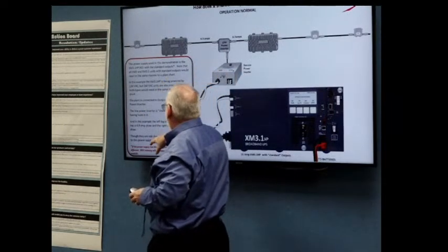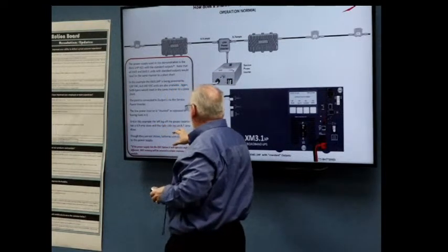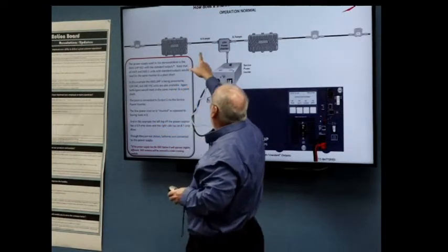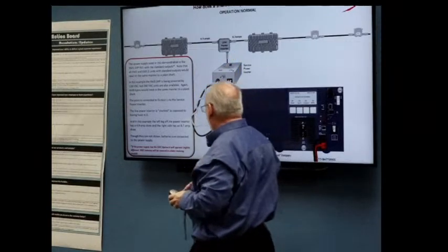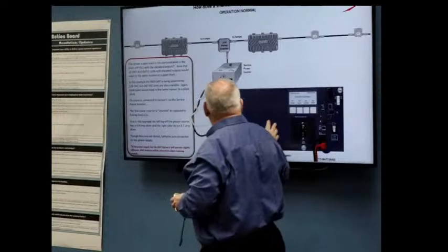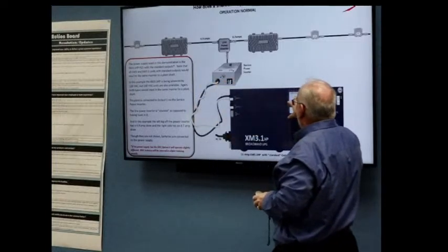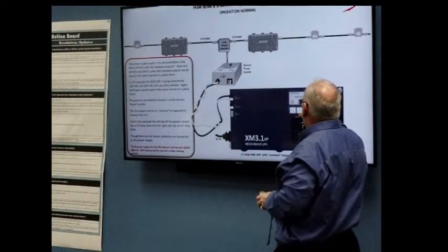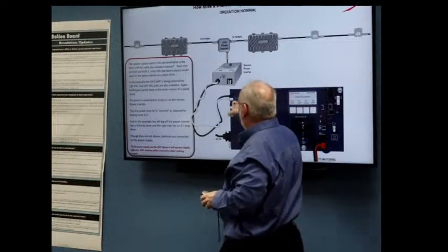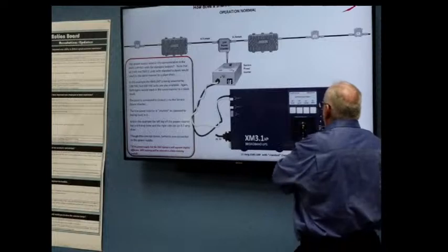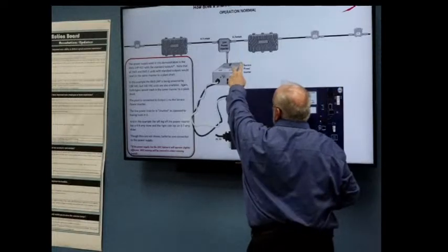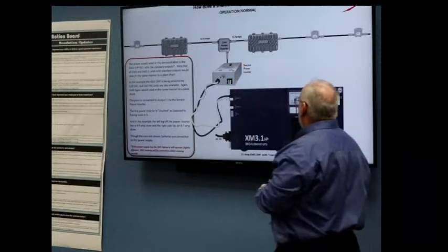Okay. In this example, the left leg off the power supply has a 4.9 amp draw. The right one has an 8.7 amp draw. So though they're not shown, batteries and everything are connected. What you'll see on the power supply is 89 volts. And again, that's my launch voltage, right? It's going to drop, but that's my launch voltage, at 13.6 amps, which is effectively those amps added up.